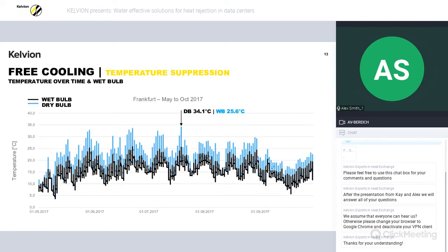And this is where wet bulb temperatures start to come into effect. So the wet bulb temperature is the lowest temperature we're able to pre-cool the air to with the use of evaporating water. Cooling towers operate at this point instead of the dry bulb because they rely solely on the evaporation of water to cool down a process. In this case, a cooling tower is designed at 25.6 degrees Celsius instead of the 34.1 degrees for the dry